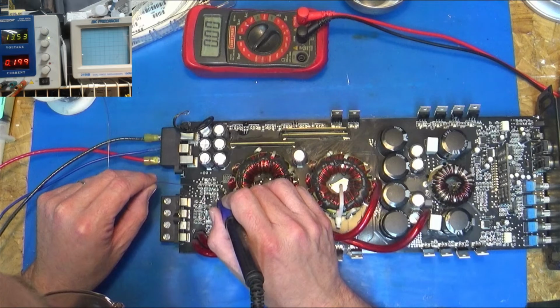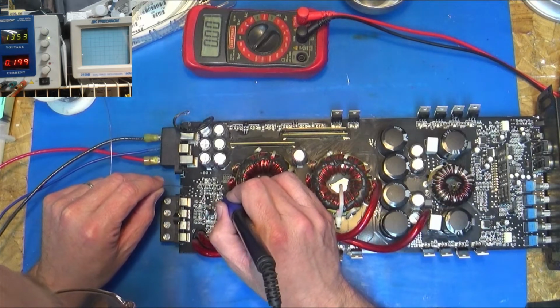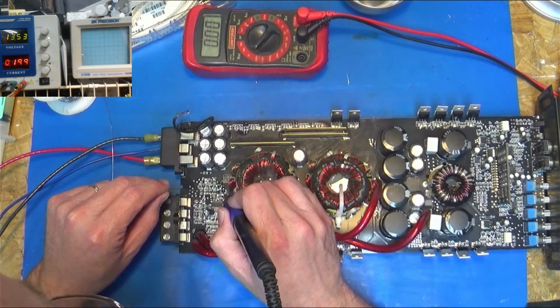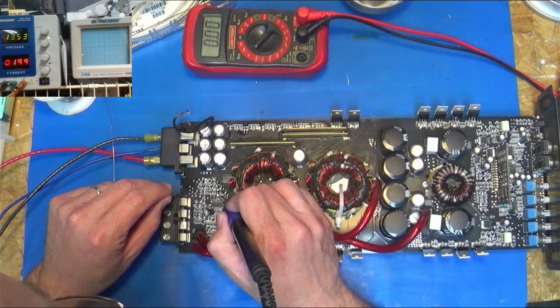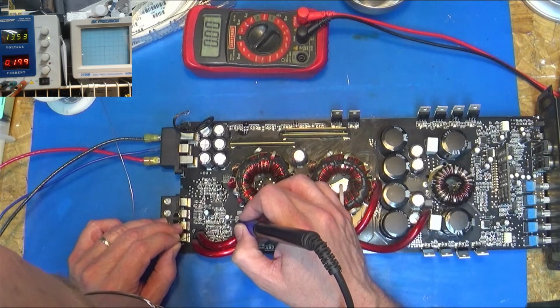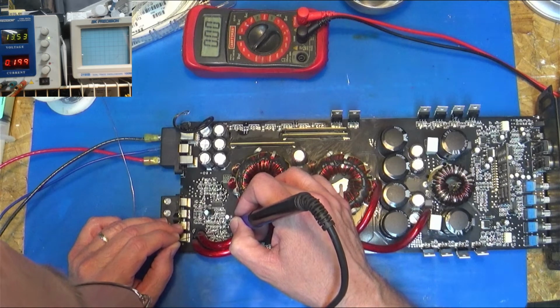And so I'm just getting some leaded solder, and what that is doing when I'm mixing that with the lead-free solder is lowering the melting point. And the reason why you want to lower the melting point is so that you don't blow off all the other components that are here.